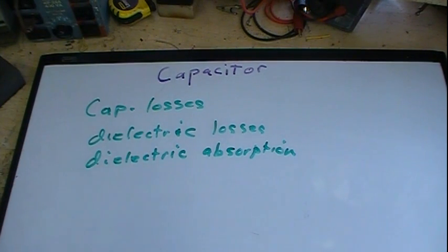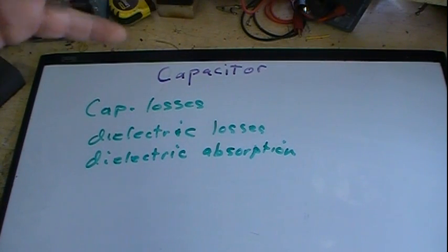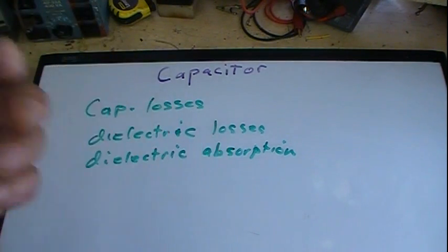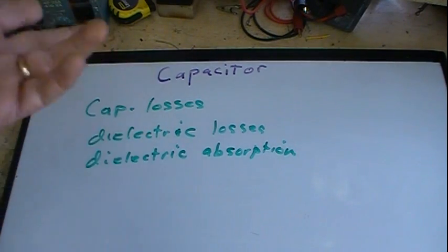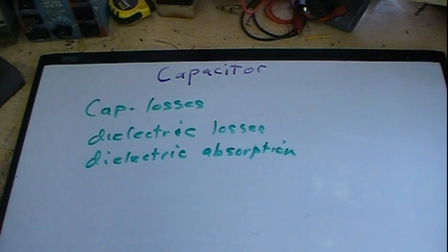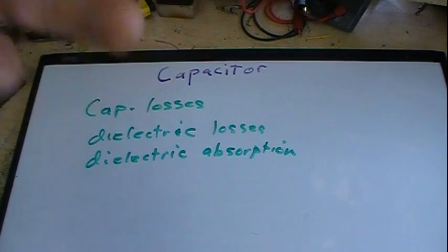Why did you get a shock? It's because of the dielectric absorption. They don't like returning back to their original positions very quickly. They stay in those positions, which will then create a static charge on the plates, and effectively you get a shock when you touch them, if it's had a high enough voltage on it. If it only charged up to 10 volts, you're not going to feel anything. But this is why a picture tube will hold a considerable amount of charge and will rebuild it even if you do short it out.